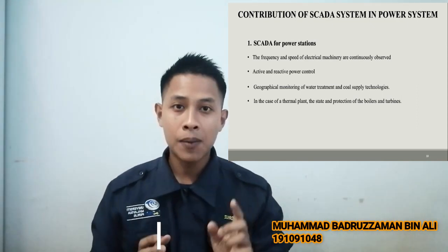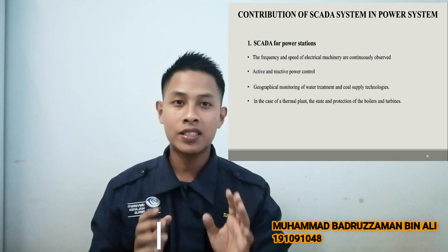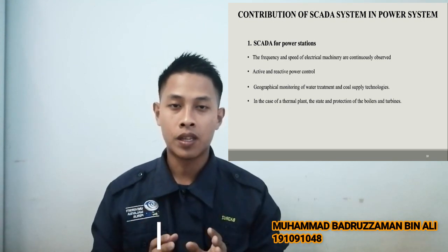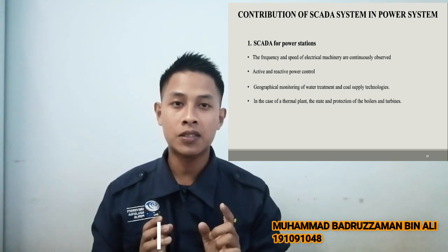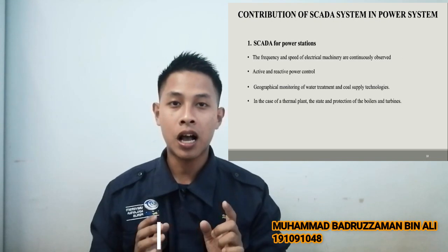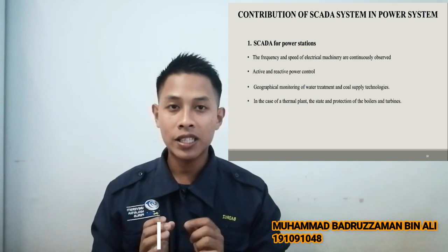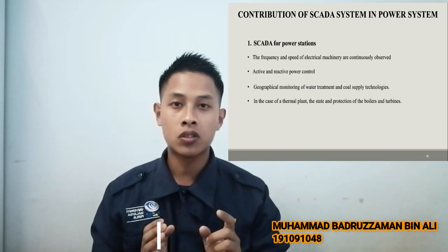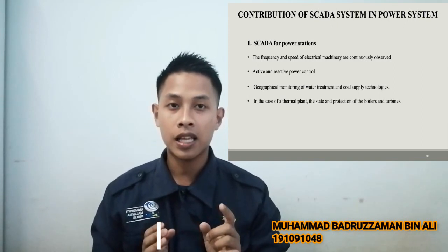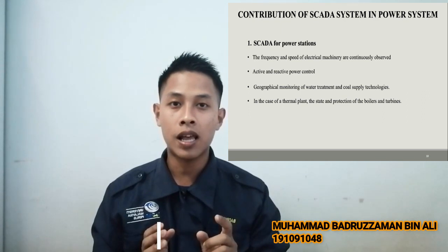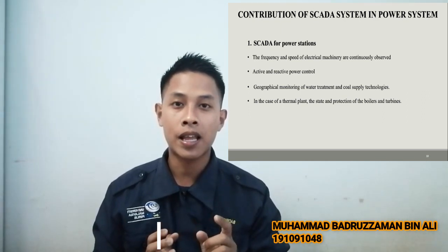In a power plant, some of the most important SCADA functions are as follows. First, the frequency and the speed of electrical machinery are continuously observed. Second, geographical monitoring of water treatment and source supply technology. Third, active and reactive power control, and lastly, in the case of a thermal plant, the state and protection of the boiler and turbine. Next, SCADA in transmission lines.